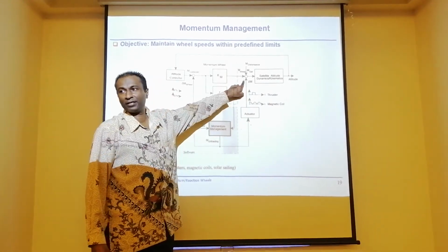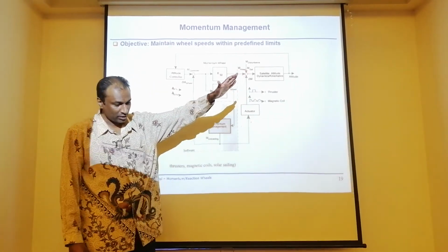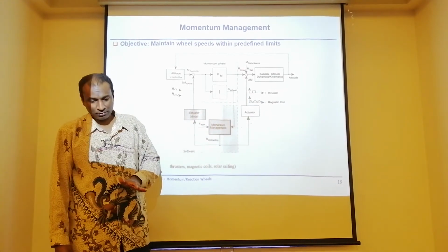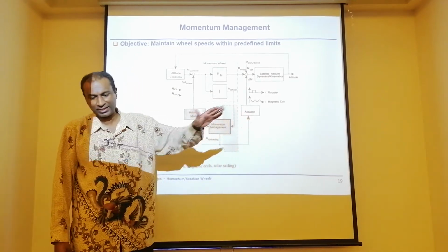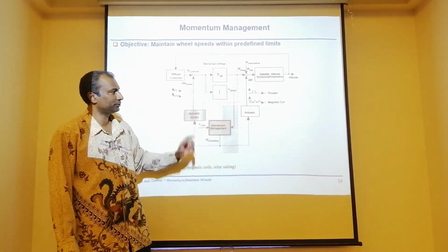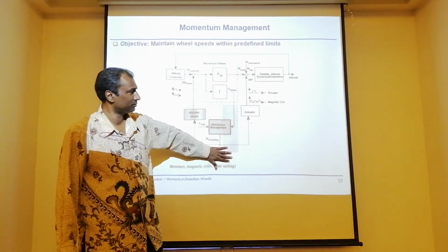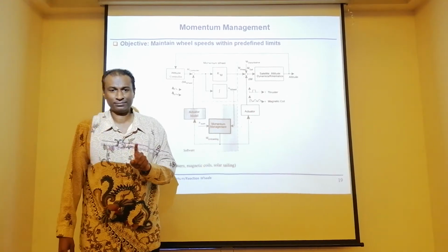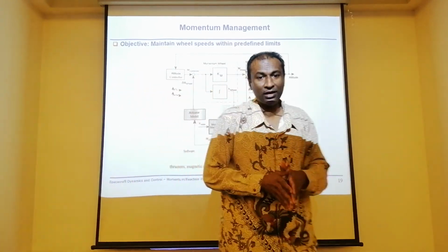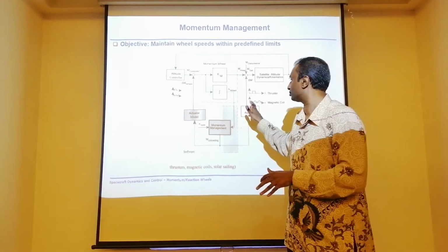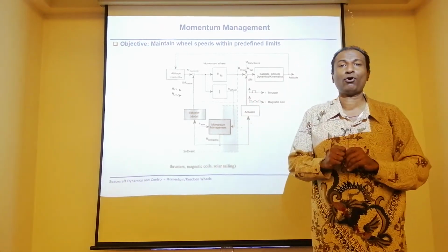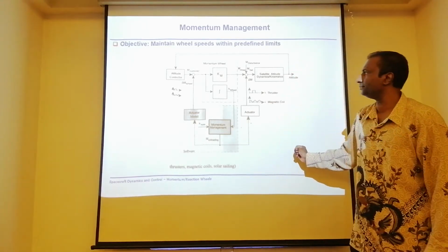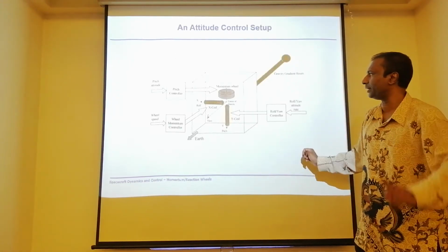Positive torque, this gives you negative torque. With negative torque, the wheel will slow down because it produces negative torque. You accelerate, you have positive torque. Decelerate, you have a negative torque. Again, another option, you can always use thrusters, but expensive. Best use magneto torques. Thrusters keep for orbit control. You can live longer, especially for satellites.